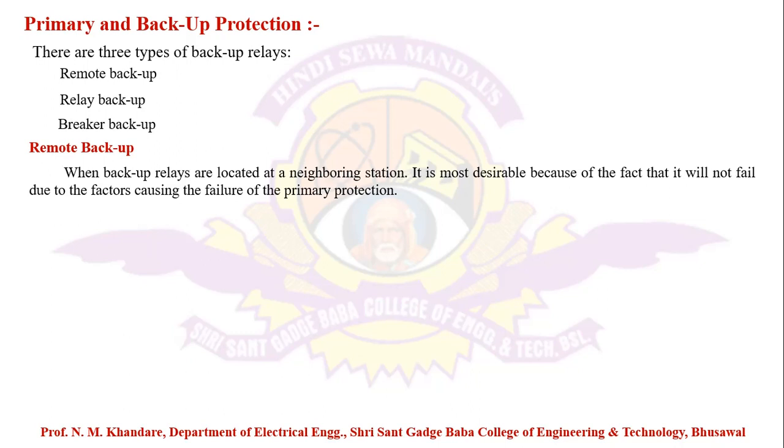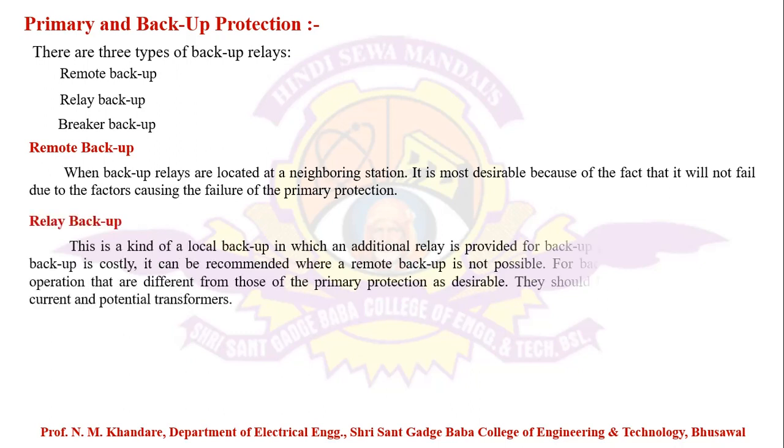Next is the relay backup. If the protected zone is situated far away from the neighboring substations, then it's impossible to provide a remote backup because it becomes costly as well as the performance may be lowered. That's why we are providing additional relays for the backup protection, and they operate the same circuit breaker for which we already provided the primary protection.